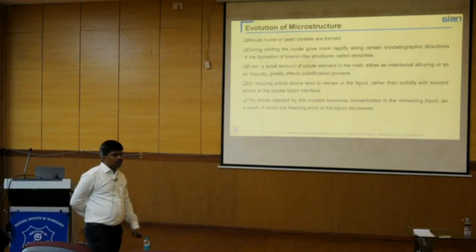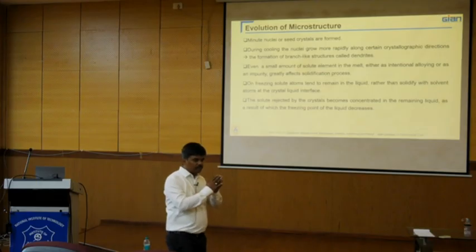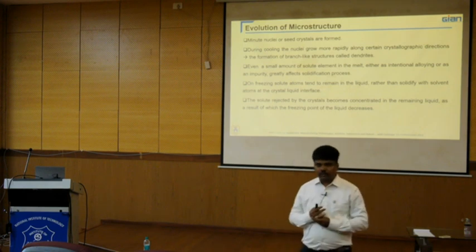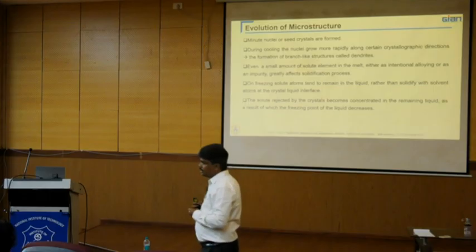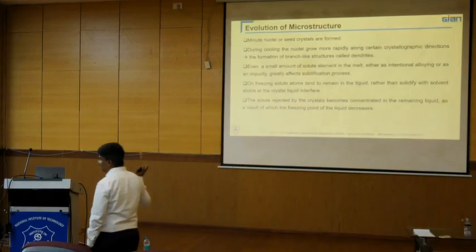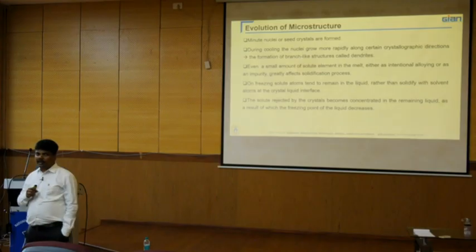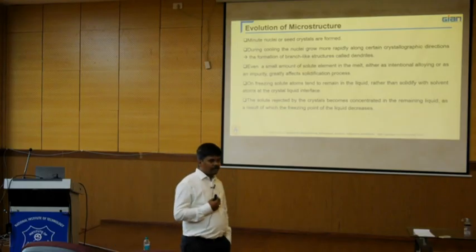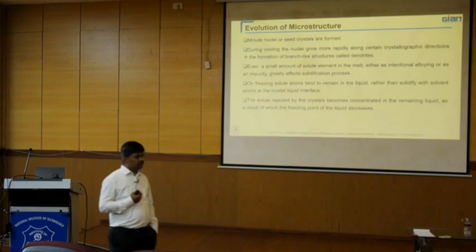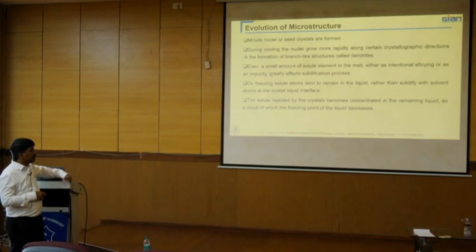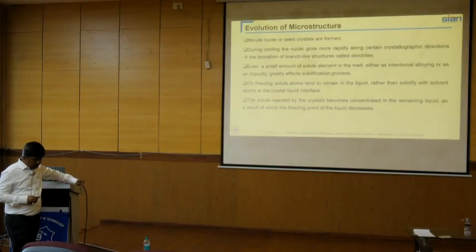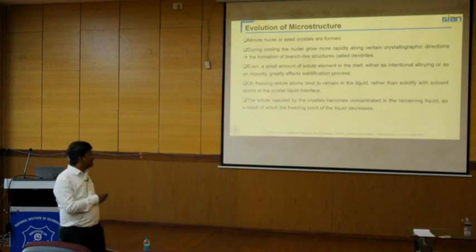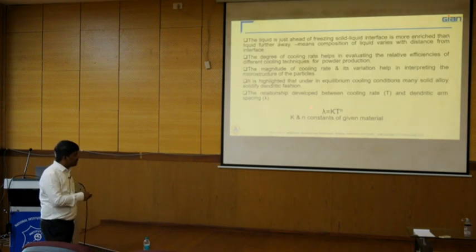And how does the microstructure evolve? Okay, the powder particles are broken into ligaments and then droplets. In our additive manufacturing process, we are going to get columnar dendritic structures, but will that follow the powder particles? Why are we having these kinds of dendritic structures? What is the major scenario with respect to this? Because of the rapid solidification. When these powder particles rapidly solidify, the crystallographic directions grow in all the directions during solidification. With that, it depends on lambda,